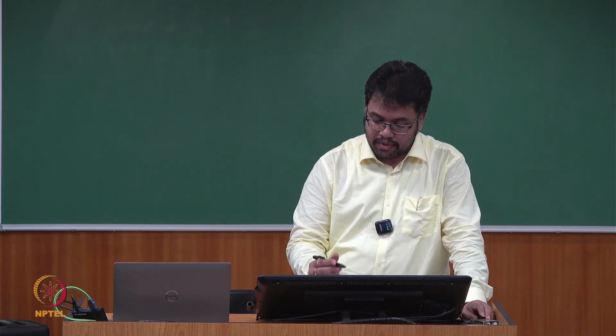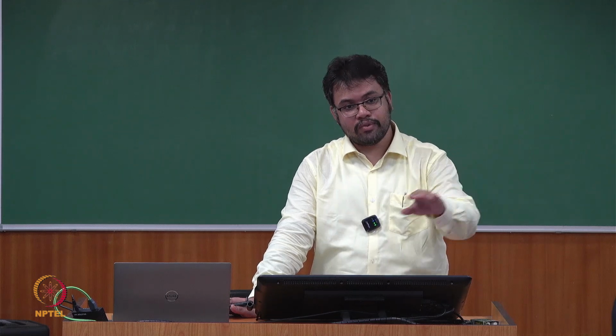The complementary part of the solution dies out with time, because it has a damping coefficient, that is e to the power minus psi omega t. This is always a decaying function. As time increases, e to the power minus psi omega t decays.